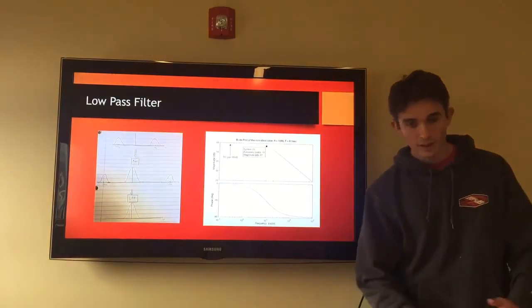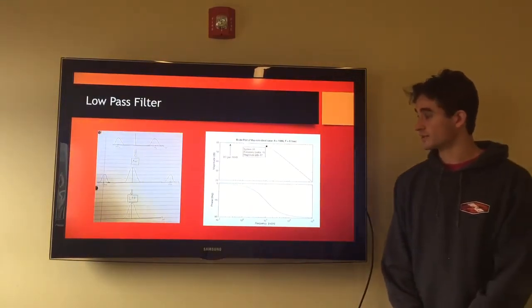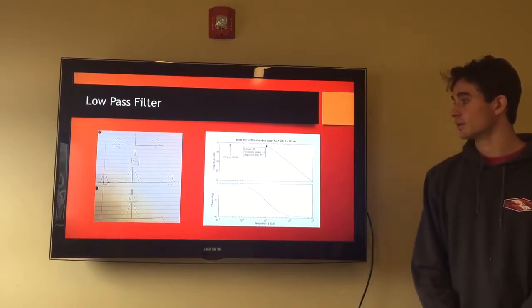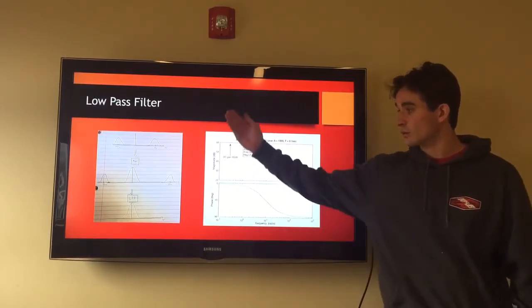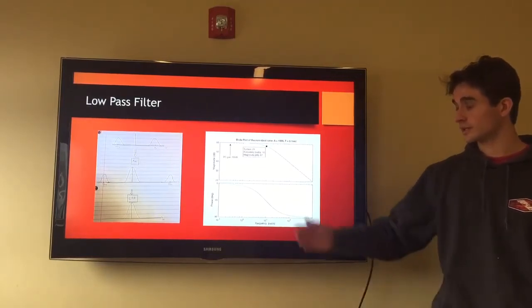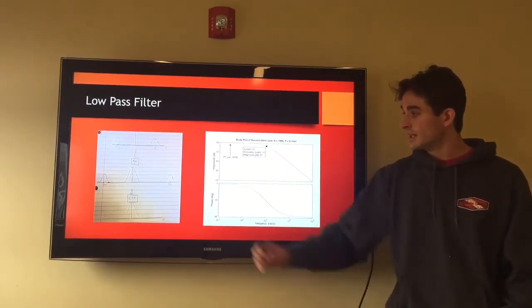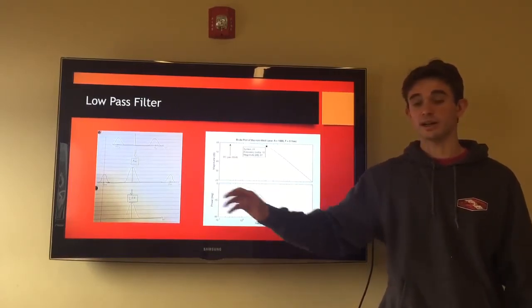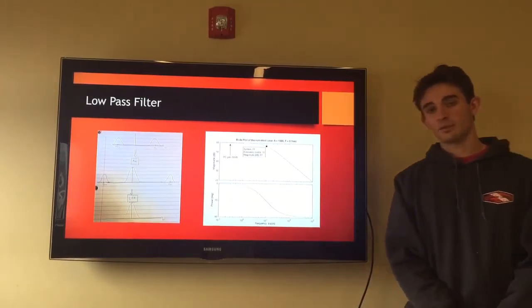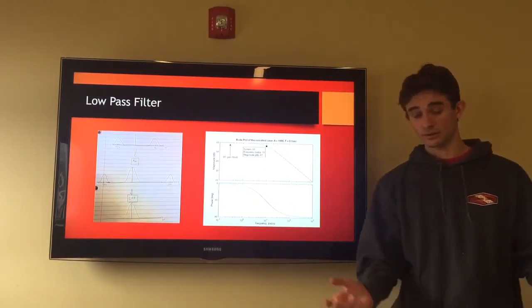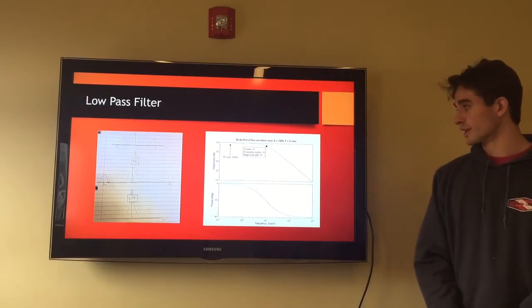So lastly, we have our low pass filter. With our mixer, we've mixed the signal, and now we send it through a low pass filter. What the low pass filter does is get rid of those 2 copies at 2 omega naught and minus 2 omega naught. So we're left with our original copy of X of j omega, our voice signal that we sent over the air.